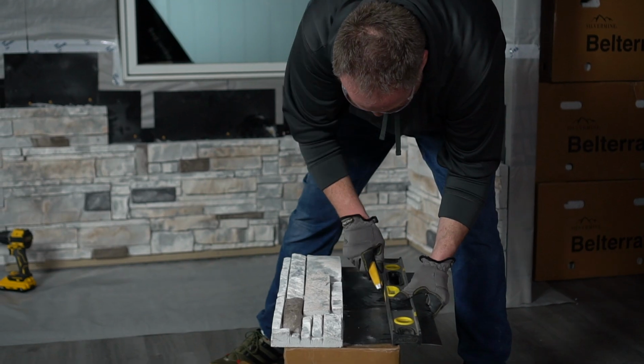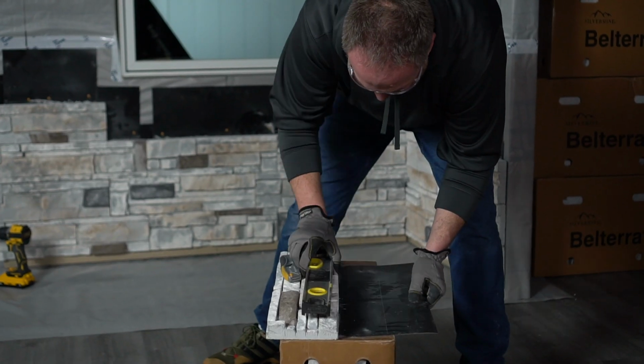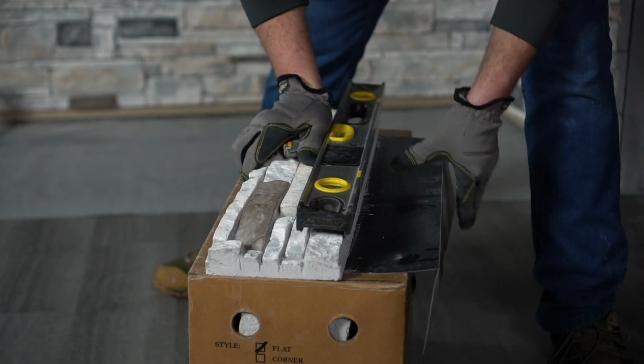Remove the trim board and cut the bottoms of the panels, or in the case of a sill, the bottom of the panels below the sills. So the cut panel or the cut panel plus the sill will fit with room for the trim board and an expansion gap. Trim the integrated flashing of the last panel so it adjoins the window frame. Dry fit with the trim board.